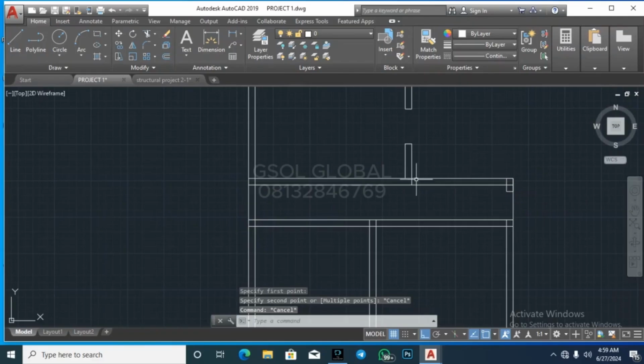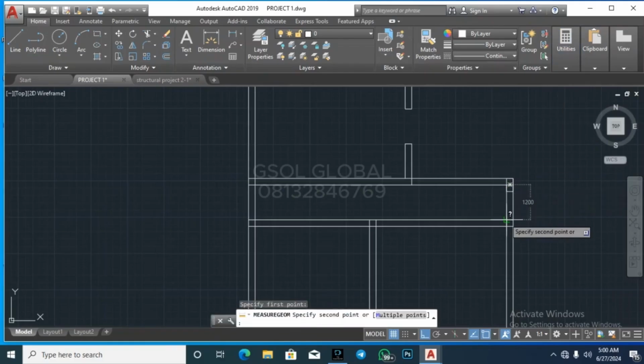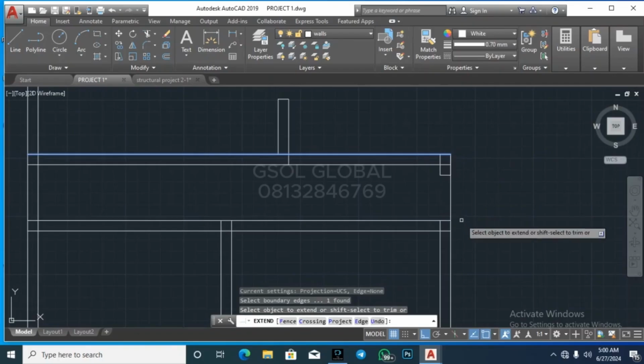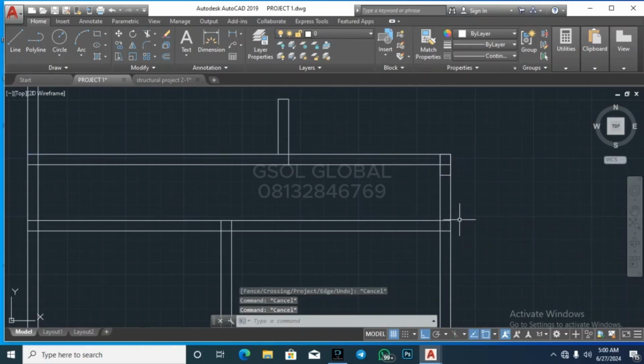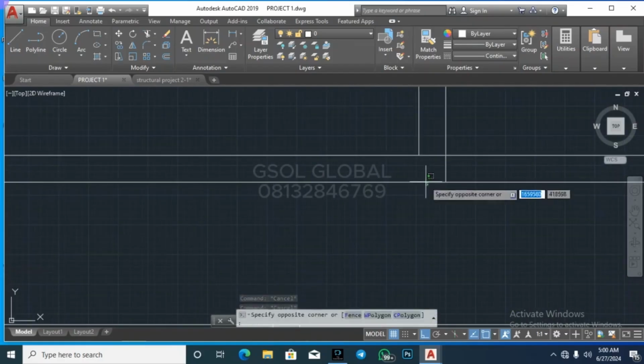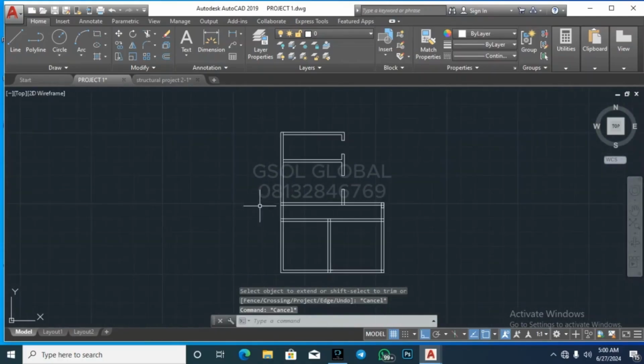All right. Okay. We'll be having a column here and a column here, so it's not too long for a beam, and also it's not too wide. The area is not too much for a slab. It's just a one-way slab. All right. For obviously, it's a one-way slab. So 1 meter, 1.2 meter is not too much. All right. So now I'm going to select this. Don't worry. Our slab analysis will give us the results and we'll see what we have, not just by mouth. All right. So if it's too much, then we'll just go back and work on it.